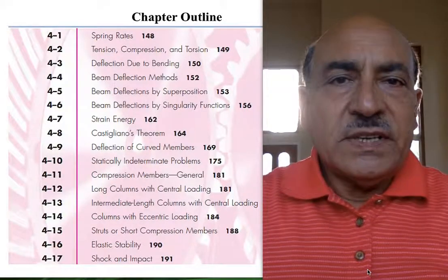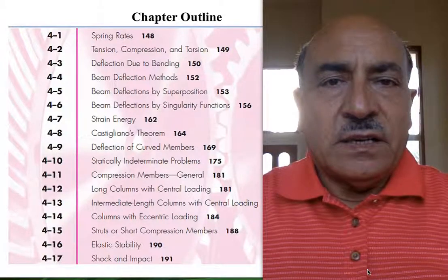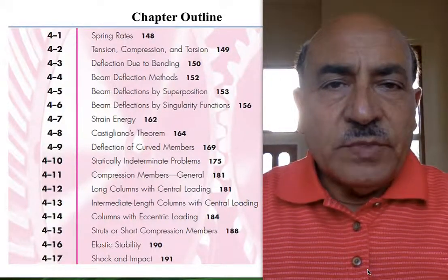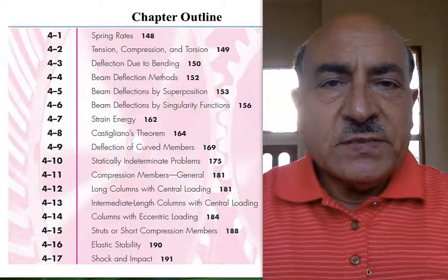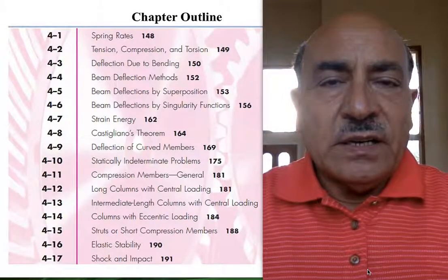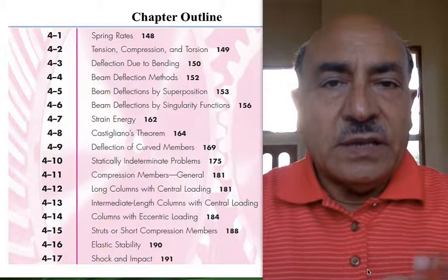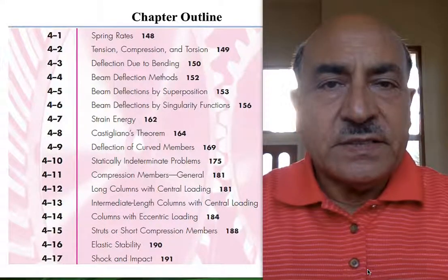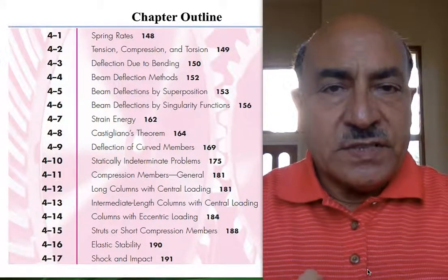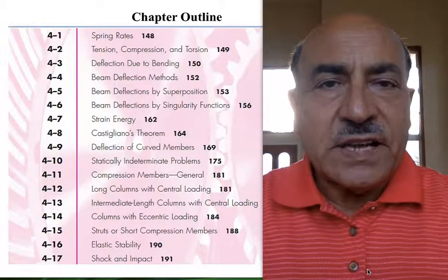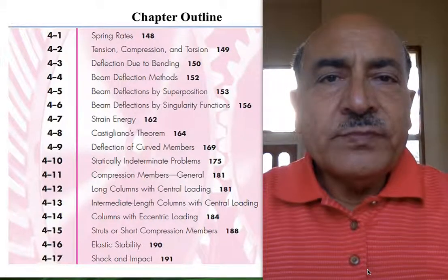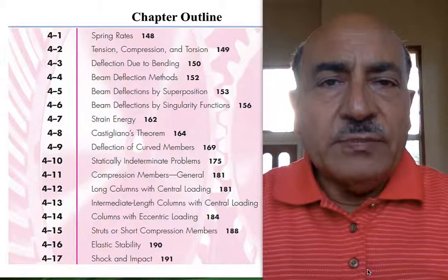However, as we will see when we apply these methods to designing power transmission, the power transmission shaft itself is considered a beam, and the shaft has different cross sections, so it's not all uniform, because you have to attach gears, for example, and bearings.